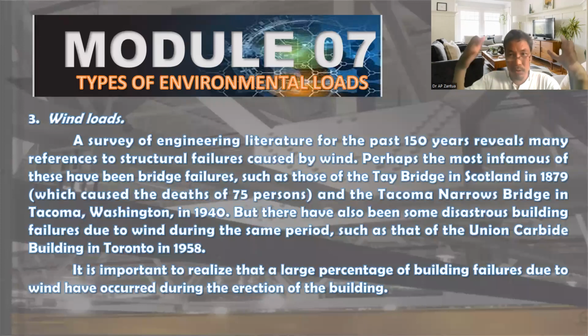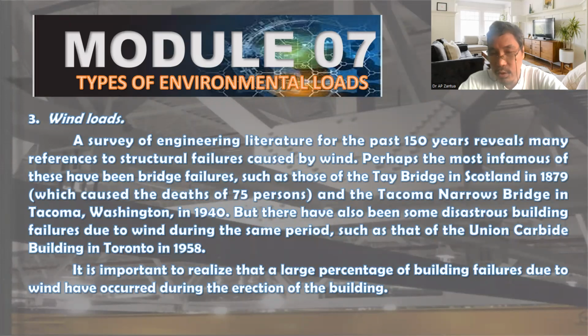Not only the weight of the wet concrete, but you also have to consider the weight of the workers and, in addition, the wind. The wind could be horizontal, could be lateral. And take note, the weakness of buildings and vertical structures is lateral loads. That is the weakness.